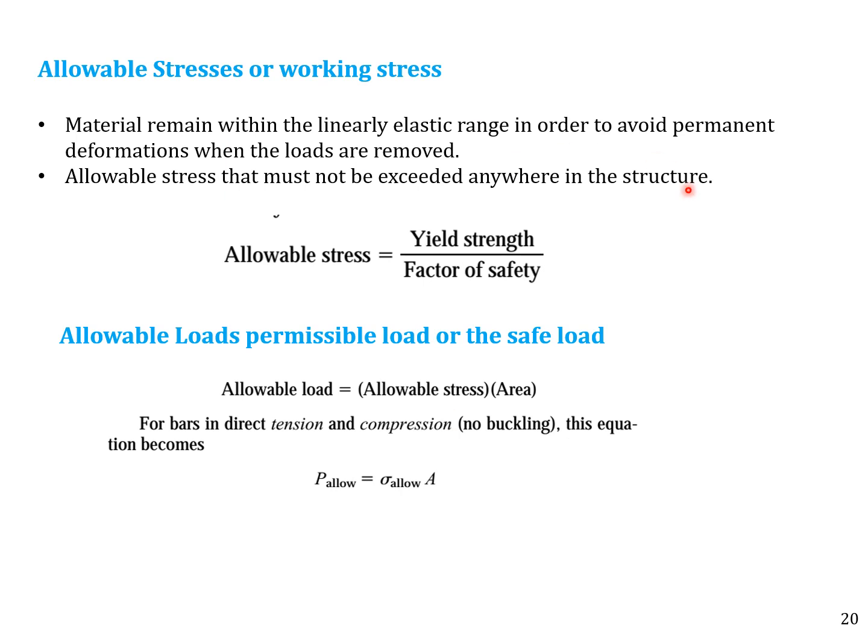Then another definition is allowable stress or working stress. It's calculated using the factor of safety, and it's equal to yield strength divided by factor of safety. And similarly, allowable or permissible load means how much load will be safe. We will calculate it again using this allowable stress or yield strength and a factor of safety. So allowable load will be equal to allowable stress times unit area.